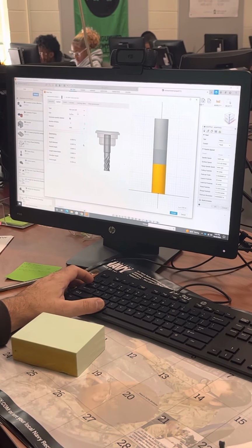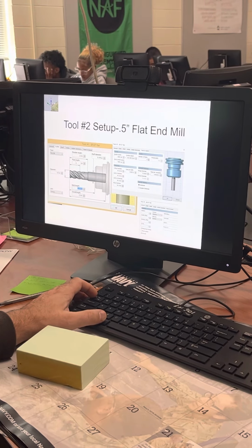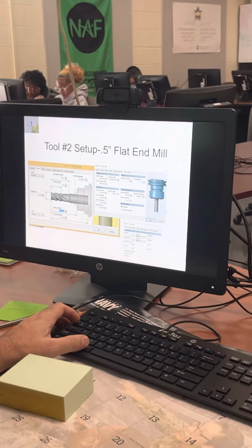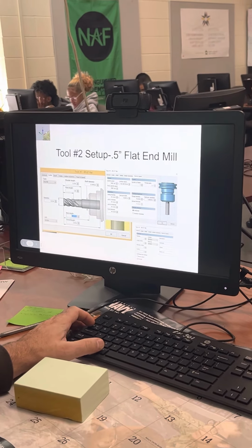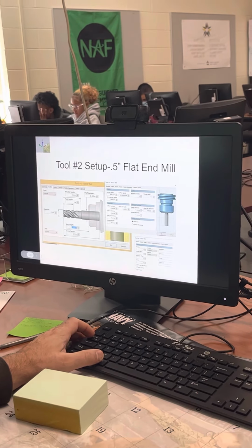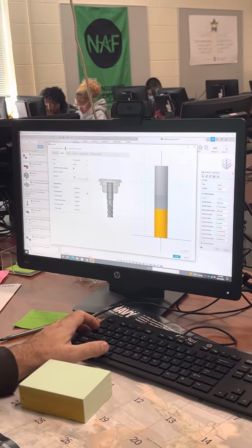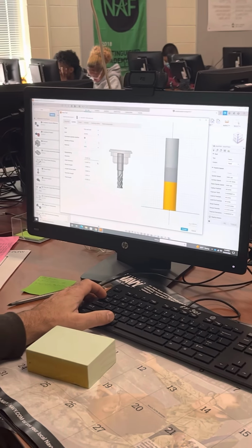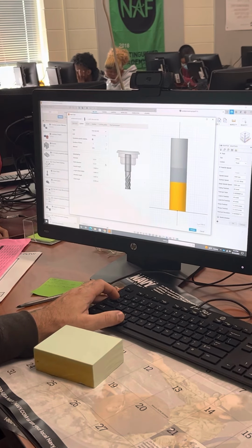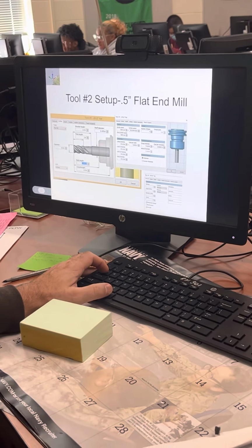All right, so flat end mill, units in inches, the number of flutes. What's it say in here? You guys see it? There's 2 flutes, there's 2 cutters, 1, 2. I don't think it's mentioned anywhere else, is it? I don't see it. So 2, we'll use HSS steel, diameter 1/2 inch. That changes overall length. What's the overall length? 2.5. See from here to here? 2.5.